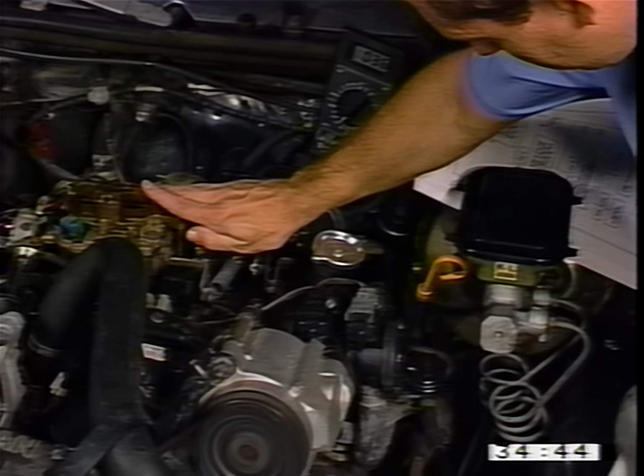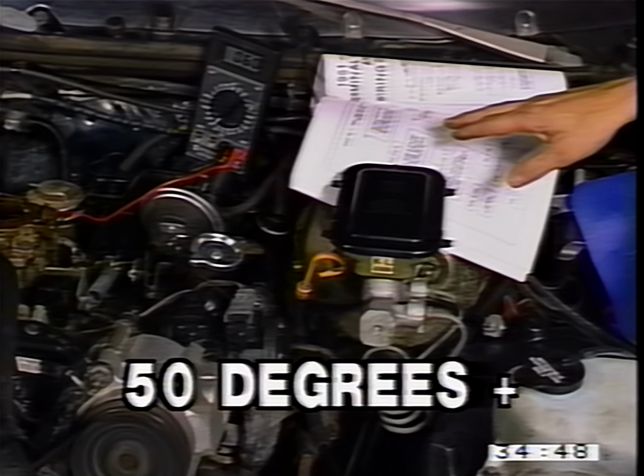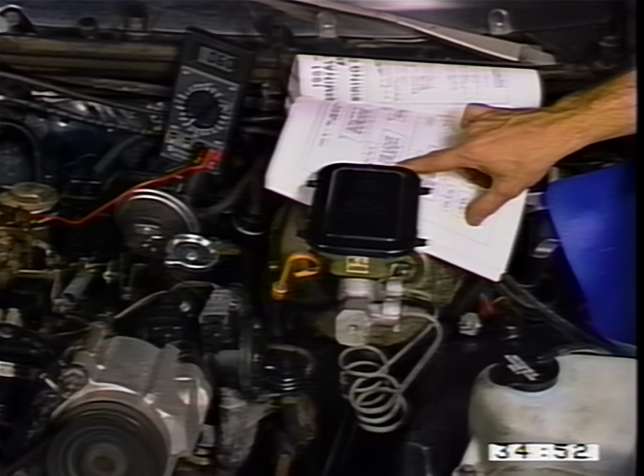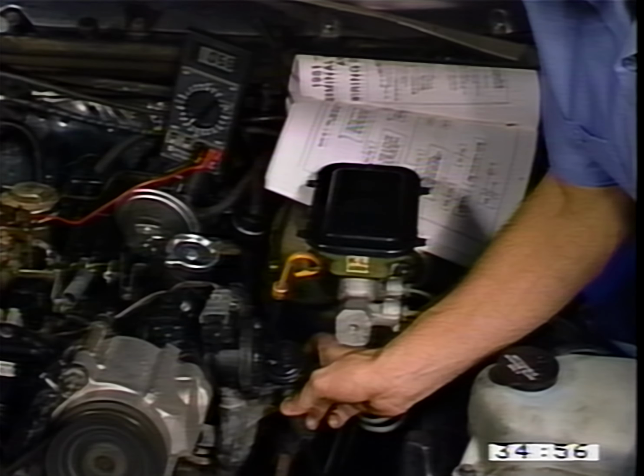There are 3 possibilities. Dwell will be 50 degrees or over, in which case you're instructed by the service manual's decision tree to service the carburetor, including its adjustment. A faulty canister purge may also cause this condition.